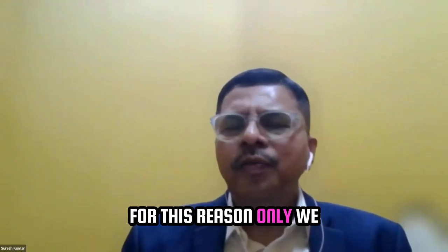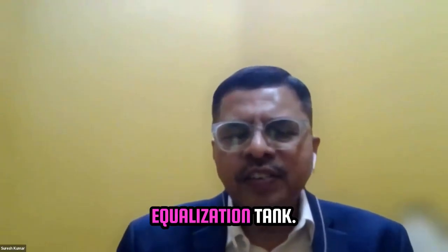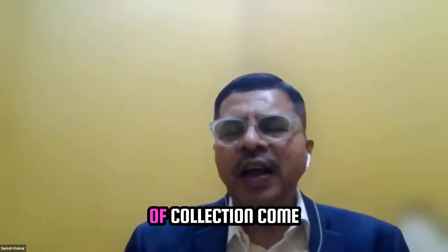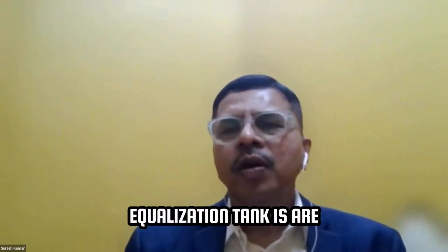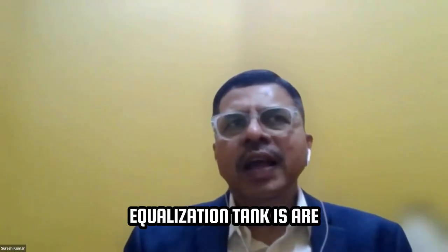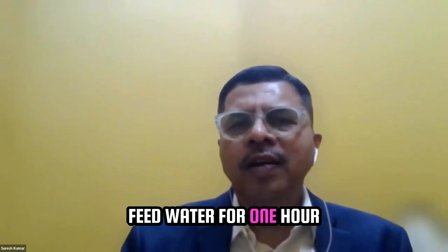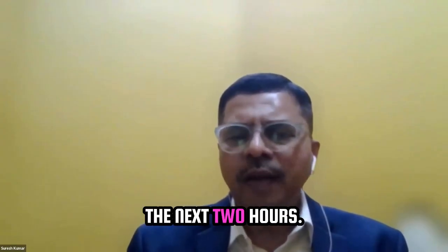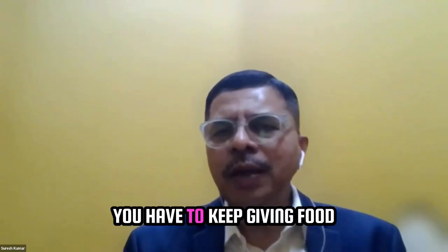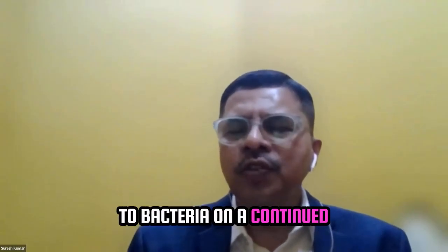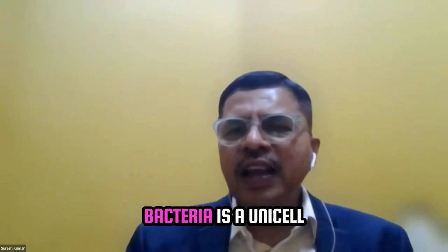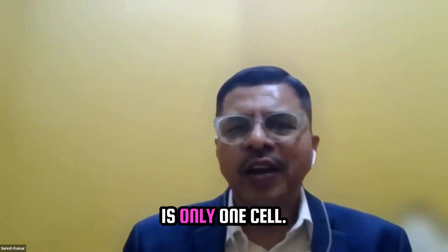For this reason only, we have a collection cum equalization tank. The purpose of the collection cum equalization tank is that any biological treatment plant is not designed to feed water for 1 hour and stop the process for the next 2 hours. You have to keep giving food to bacteria in a continued, sustainable manner. Bacteria is a unicellular microorganism. There is only one cell.